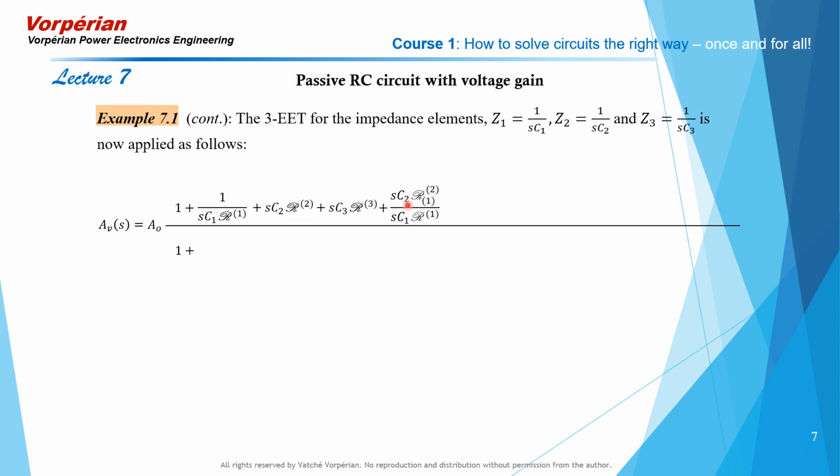But when we bring in z2 next, that is to say we pair the second port with the first port, this time the impedance that accompanies the impedance element z2 is the null impedance looking into port 2, but this time with port 1, that is to say the port with which it is being paired, in the opposite state of its reference state. And that's the difference between this term here and that term there. This here is the same as that one.